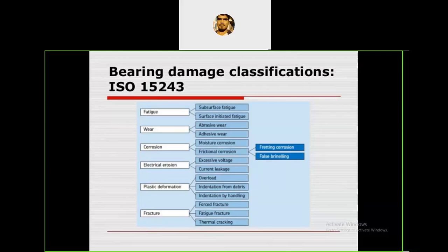So with this, we discussed so many types of wear. The first type of wear is adhesive wear. Adhesive wear means one surface adheres to another surface, bonding over the other surface. That is called wear. Second, abrasive wear means one surface containing a hard projection will block the other surface, or contamination from foreign particles will create scratches on the other surface. It is also abrasive wear.